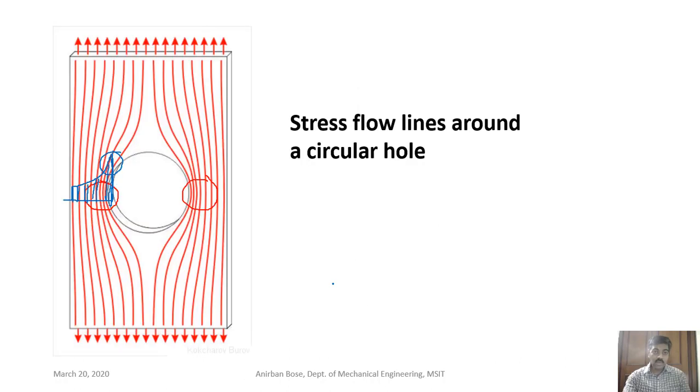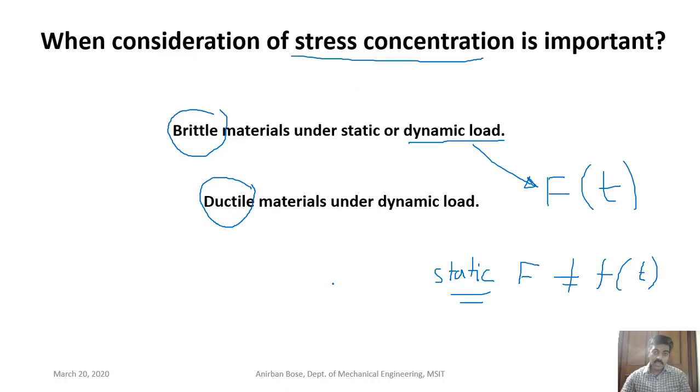Okay, so dynamic load, we'll discuss in detail in the next topic on fracture mechanics, how stress concentration is important in dynamic load and all that. But right now the takeaway points from this slide are: if it is dynamic load, then stress concentration is very important irrespective of whether it is ductile or brittle.